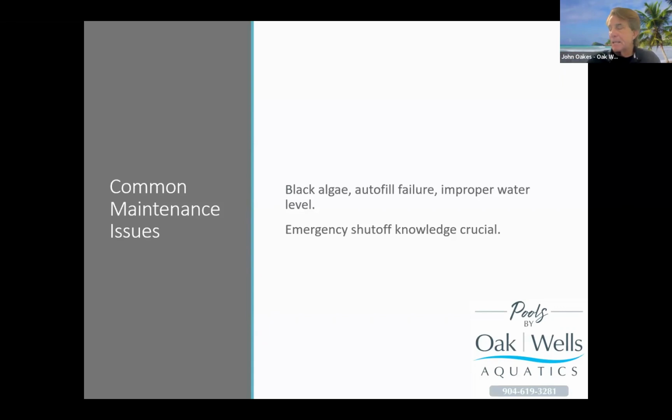The simple test that I alluded to earlier is if you turn the pool pumps off and take your camera or your phone and take a picture of the water level when the water's still, just right at the water line on the tile, you can see it. In a corner is the best place to do it. And then take a 5-gallon bucket, set it on your pool deck, and fill it up to the very, very top and take a picture of that.